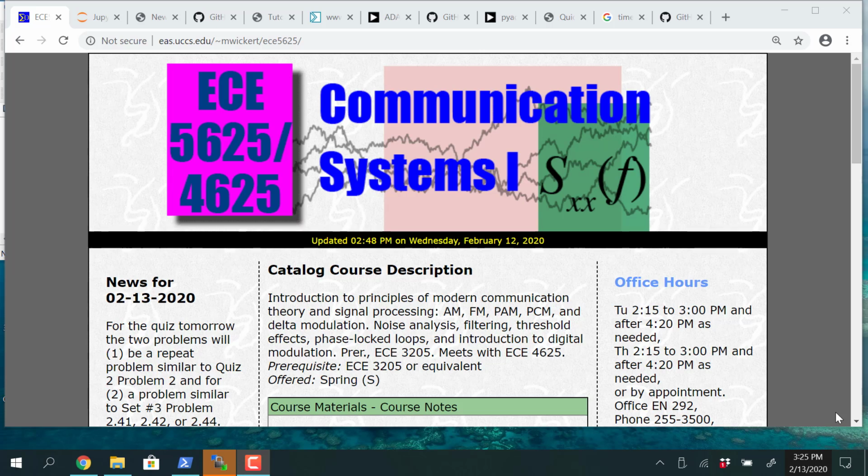When you Fourier transform a cosine wave, you get half of the spectrum at the positive frequency and half at the negative. You didn't have that half scenario to factor out, which means double the 15 to 30, because 30 halves is 15. Yeah, it's 15 in the frequency domain. And then it gets doubled back in the time domain, because when you start in the tau domain or time domain, you just play it backwards. You could get your answer and then say, wait a minute, if I transform this forward, I should get what I started with. Just simple.